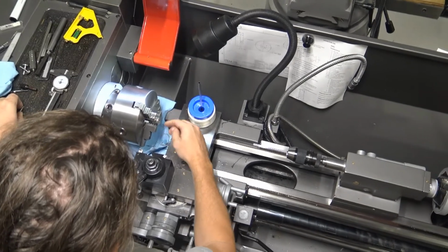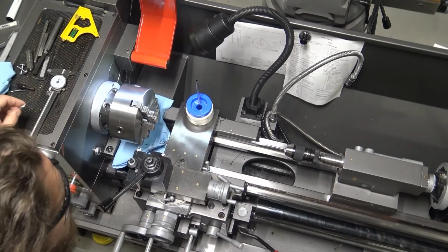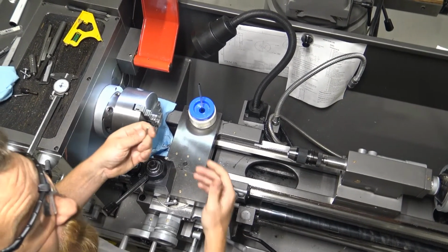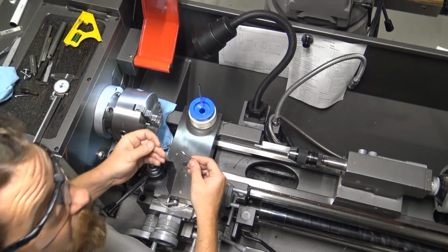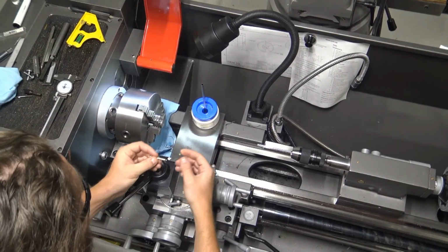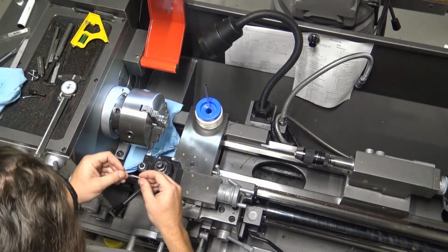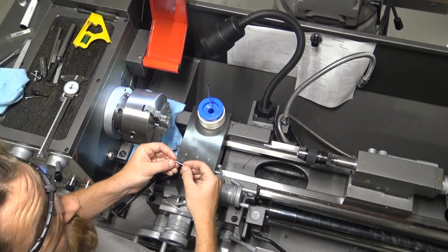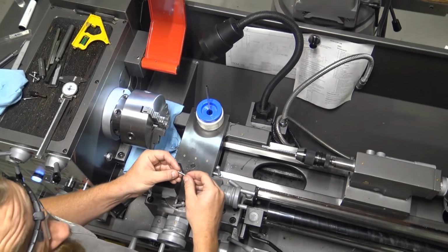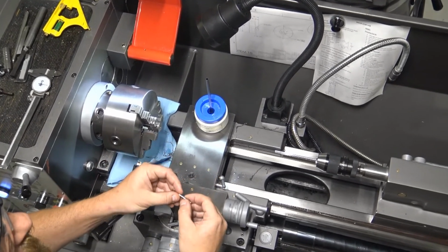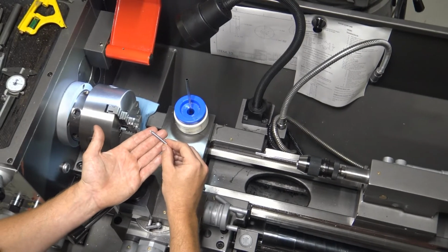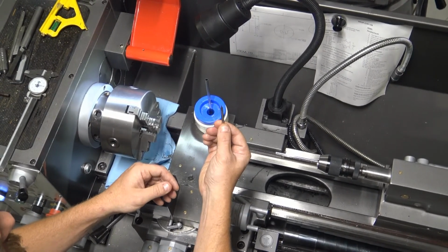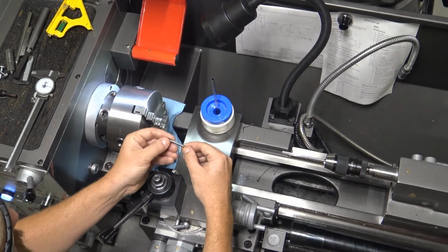One way to check to see if we used the right reamer and that the hole is the right size, we don't have a go, no-go gauge for this, but this hole is supposed to accept our flywheel. We'll actually mount it on the back of our crank, and our crank's got a 3/16 pin, which also your number 2 center drill is ground to 3/16.